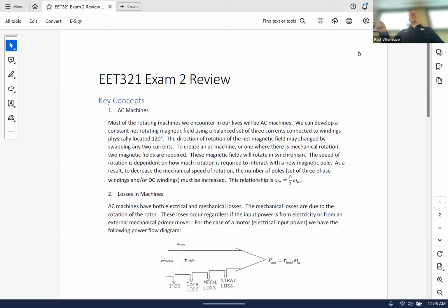And so the concept is we now have 2 magnetic fields with 2 sets of windings that are going to rotate around, and mechanically we only have to rotate half the distance to get back to where we're starting out, back with the north and the south. So by dividing that motor or that stator into magnetic halves, if you will, you actually could adjust the speed of operation. You don't need to operate at that same speed because you have that second winding that comes in. So you're basically getting back to the north and the south. And again, magnets always try to line up. So if you have one spinning here and another one spinning here, it only has to spin at half the rate.